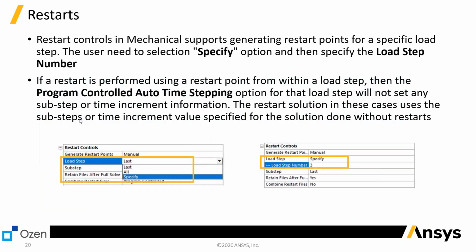Another feature is the ability to restart from specific steps. Before, people could not specify which steps to restart the solution from. It's usually wherever it stopped. But now you can specify a specific load step to restart your simulation that you paused at any time, and then you can restart from the step of interest to you.